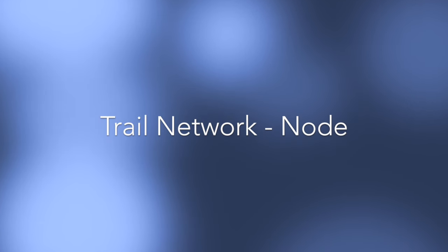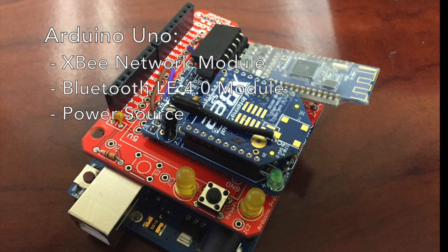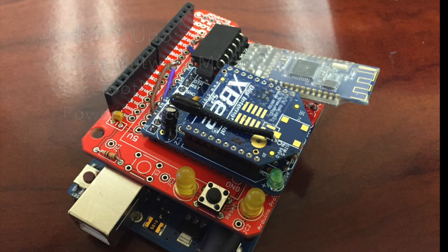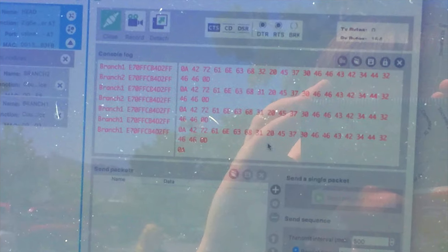Now let's check out the node hardware. The satellite node is controlled by an Arduino Uno and consists of a Bluetooth 4.0 LE listener module, a Zigbee wireless protocol mesh module, and an external power source. These nodes are placed along the trail, ideally using steel poles, but here human-powered, and feed back Bluetooth device data to the head node to be posted to the server.